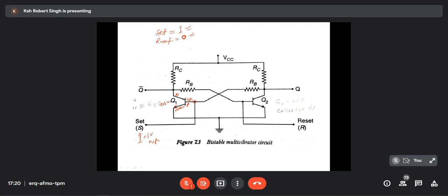If this is on, it is something like a resistor connected over here and a switch over here. This switch is closed, and there is ground. This is plus 5 volt. Earlier the switch was open, now it is closed. If the switch is closed, the voltage at this point will be ground, 0 volt, or near about 0 volt, because this is a wire. Voltage at ground and voltage over here should be the same, because there is no resistor here. Strictly speaking, there will be a little resistance drop because of the connecting wire, but that will be neglected. So around 0 volt I can say, or low.